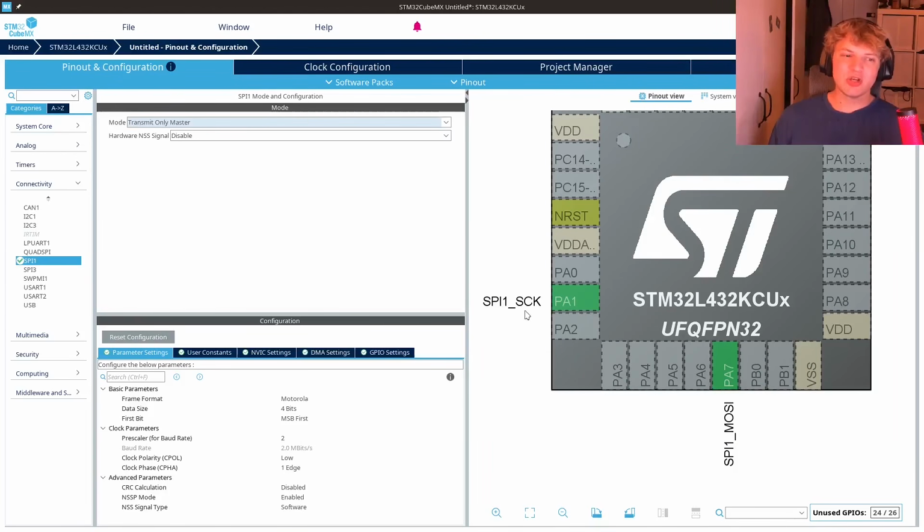And we can actually go ahead and change these to a different one. You'll notice that if you click on one of these pins, you can get a whole list of alternate functions. You'll notice we can change other things about the SPI controller as well, like the data size and the speed. I'm going to leave these for now as default. They are incorrect in the default settings, as they usually are, unless you get super lucky. But right now, for our schematic, I only care about pin definitions, so I'm going to leave these for another video.